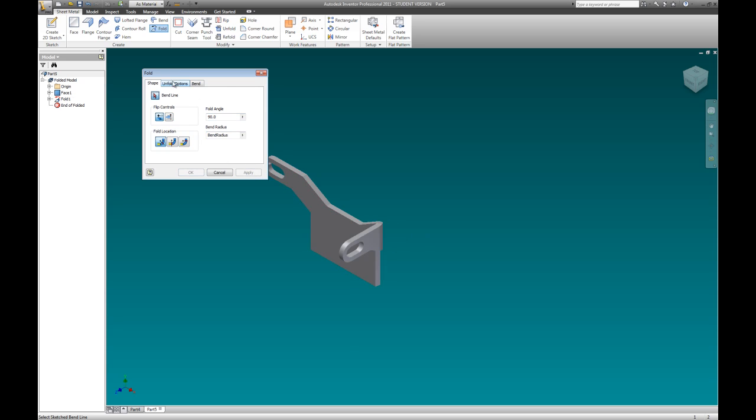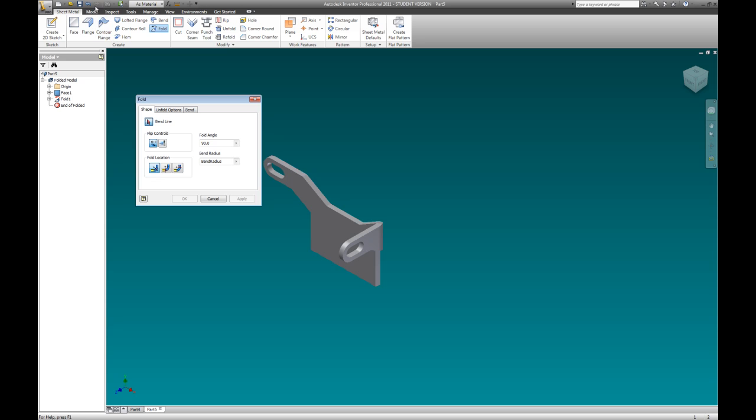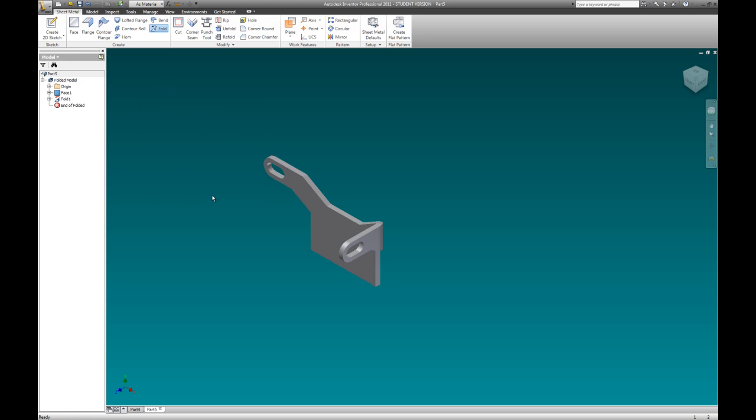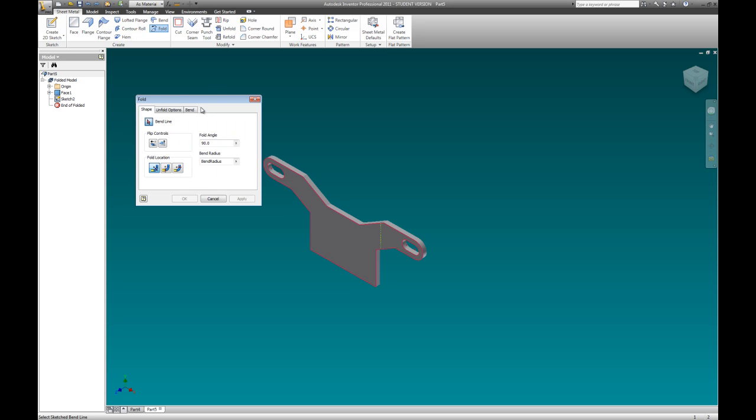Okay. And then we'll do an undo. So cancel and undo. Now let's take that again. Let's go fold. We pick our plane. Okay, the body's going to fold towards us, so I'm going to change that. So it's the ear and I'm going to change the direction. And I'm going to fold it. You can see that we can fold from there or here.